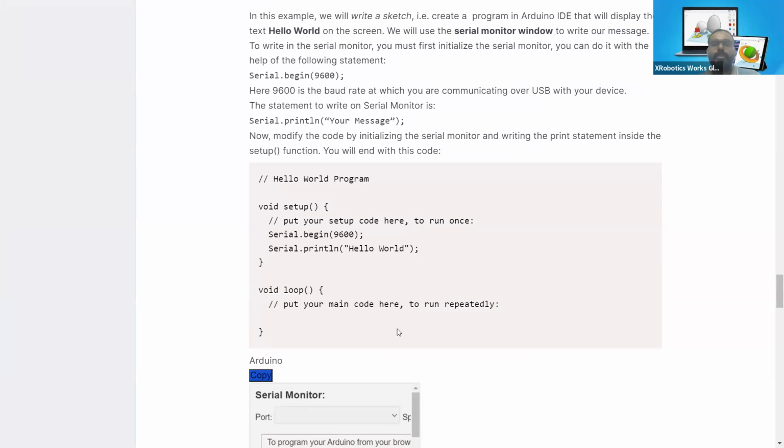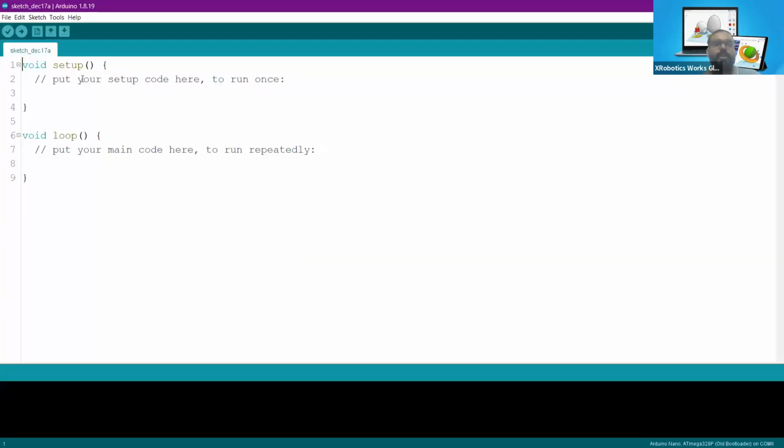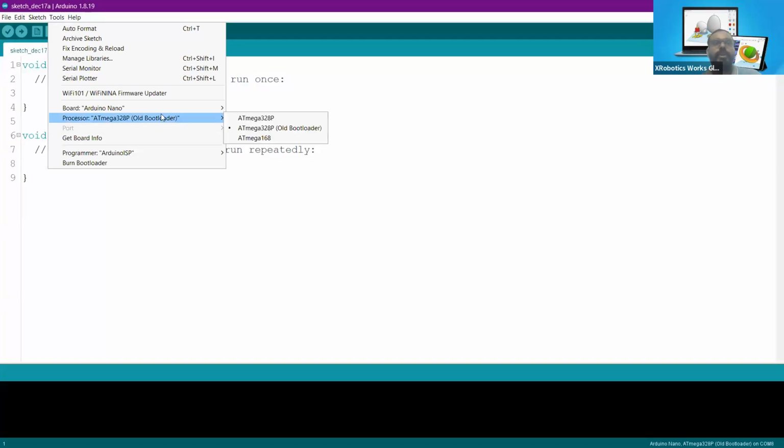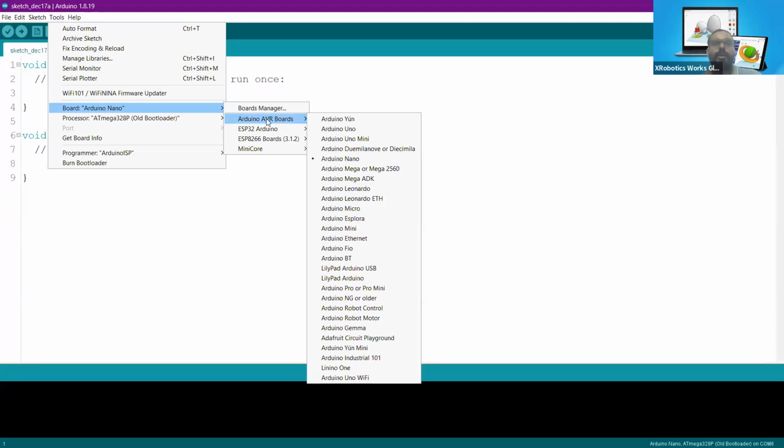Let me open up my Arduino IDE, so that I can show you the new part. Okay, I'm closing the IDE and opening a new project. Let me share my screen for the Arduino as well. So I opened the new project, and I already explained how to set up everything. If you have the board, Nano or Arduino, then you have to choose the board from the drop-down menu under the tools. Under the tools menu, you will find different boards.